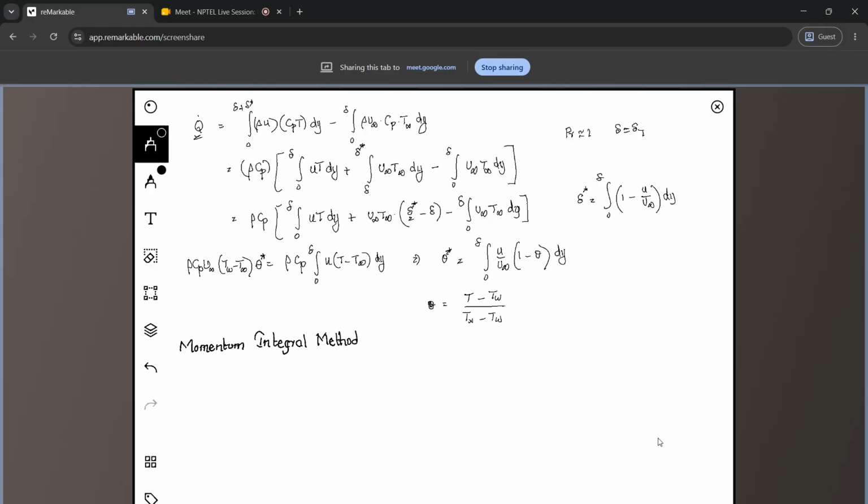The idea here is fairly straightforward. You assume you have a boundary layer, and you consider some small length delta x in that. The net force acting on this particular layer is given by the shear stress times delta x, and this should be balanced by the total shear stress that we are having, which is also given from the momentum thickness.